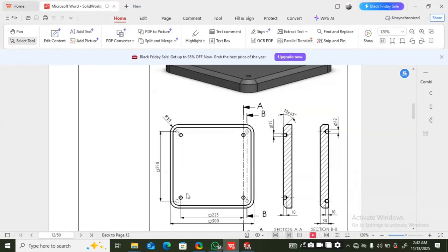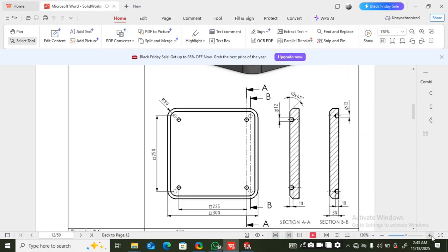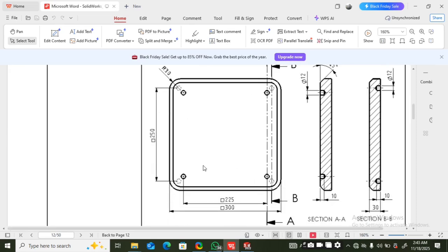So the next thing we do is to give it the respective holes. Let's take a look at something from what we can see here. We will know that there are two distinct holes. That is, this hole that has a circle here is at the front side. Then this hole that has some dotted lines is at the back of the plate, and that can be described by the model in side view.